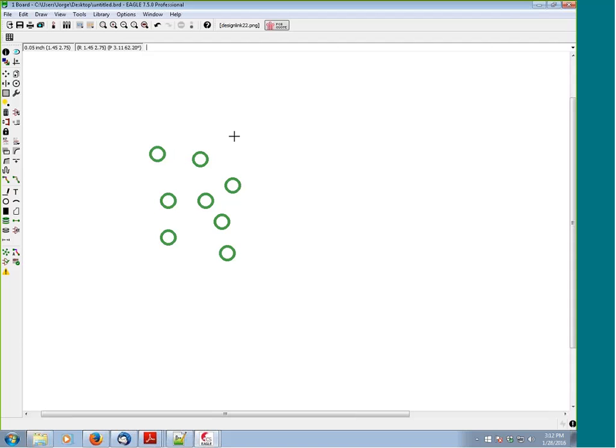That depends on the exact application. In the case of an RF board, what I've usually seen is that one way to do it is to put ground planes in between. That way they isolate what's on the bottom from the top. And then they stitch the living daylights out of it. They'll put vias all along the edges, trying to fence and create very solid paths to ground to avoid any leakage coming off the board. That's usually what I've seen. It depends on the application.